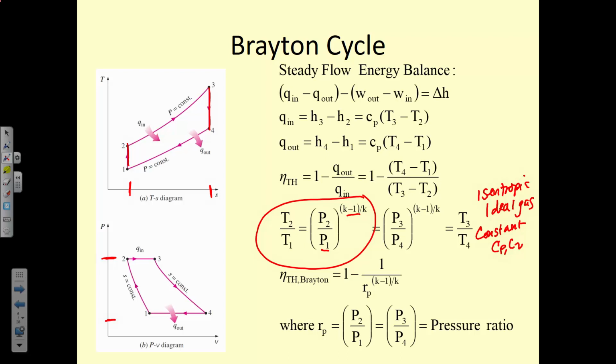On your homework, it wasn't a Brayton cycle, it was, I believe, an Otto cycle, maybe Otto and diesel. First one was Otto, then diesel, and then the second one was Stirling, and then Ericsson. On your homework that you just turned in was Otto, I think, right? Yeah. So there were some who used this equation to find the thermal efficiency on that last problem, problem 4. That would work if we were assuming constant specific heats.